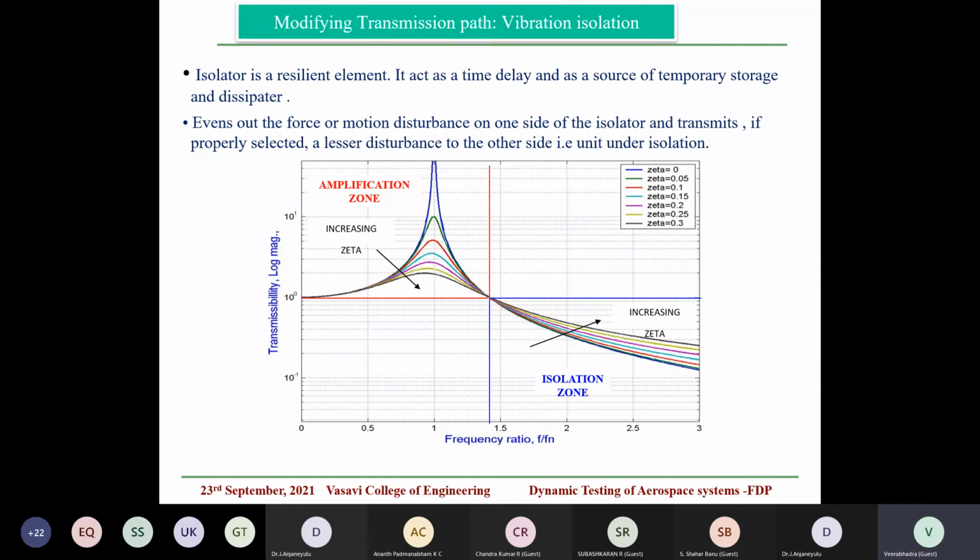Okay, sir. But at least for us, suppose I am getting 1,000 isolators, I am screening all 1,000 isolators to know the natural frequencies and then segregating them, grouping them actually. It is a time-consuming process, but you have to do it. There is no other way.